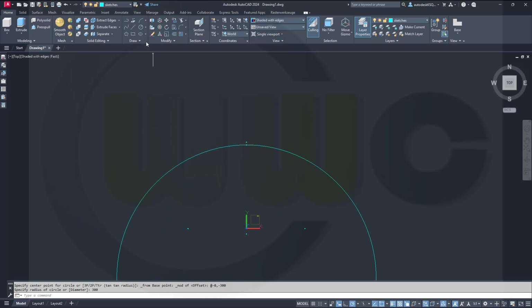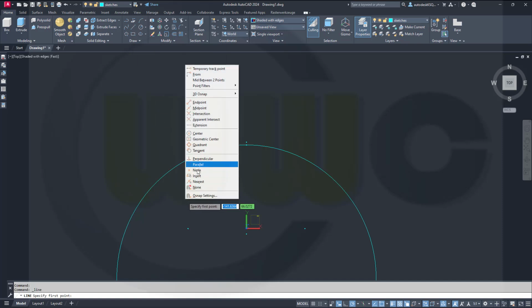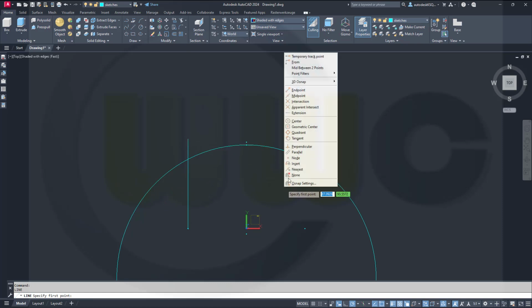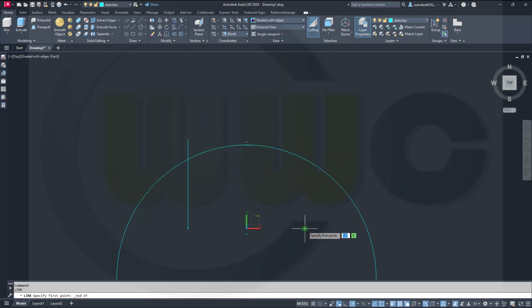Then I need lines or polylines, doesn't really matter. One which starts at this node, goes straight up like that, and another one which goes from the other node straight up. And then I will need another line from endpoint to endpoint. Now I want to trim.